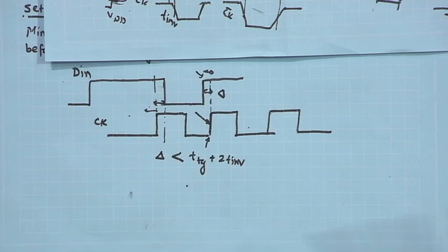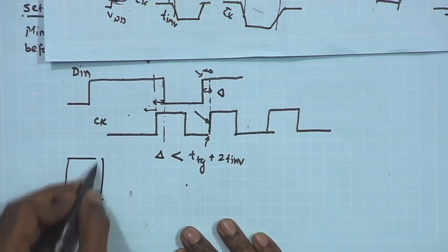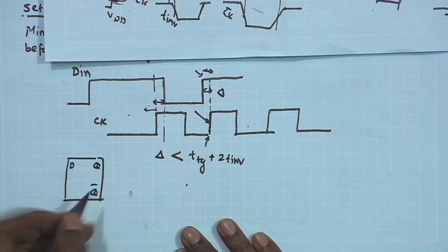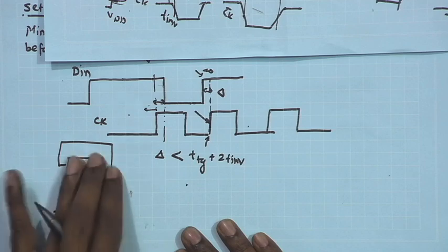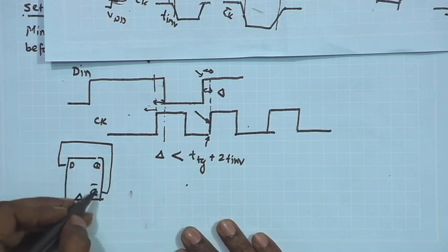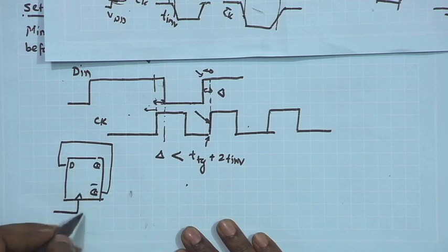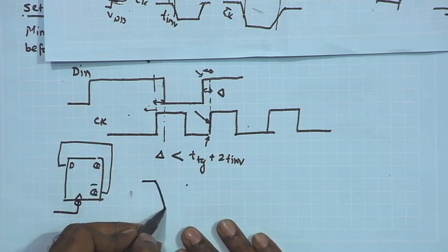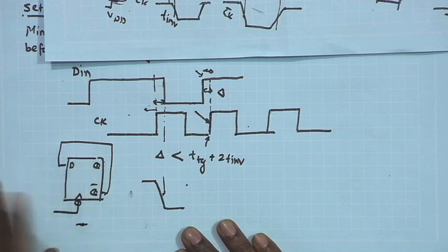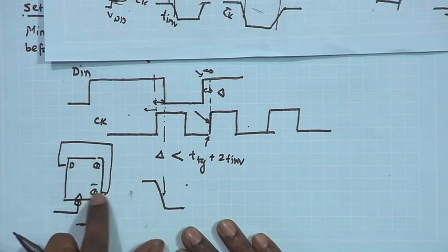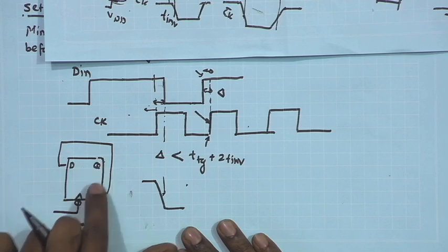If I see where we are applying this, you have the toggle flip flop being constructed, D, Q and Q bar, and we know that Q bar is connected to the D, and then you have the clock. Each element in my design has the Q bar connected to the D, and therefore, before the negative edge, in our case we have used the negative edge trigger, just for the up counting operation. Before the negative edge comes, the Q bar is anyway stable, right. Q bar is always stable because much before the negative edge of the clock, Q bar was equal to the negative of Q. Therefore, Q bar was always stable.